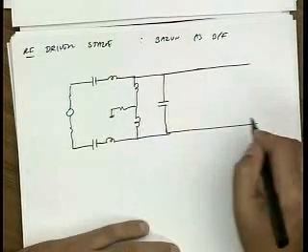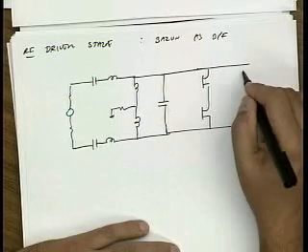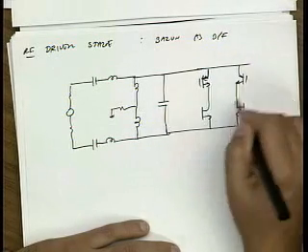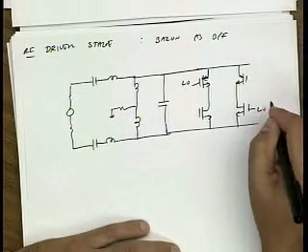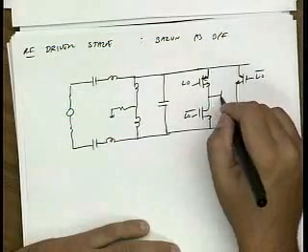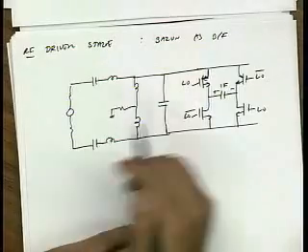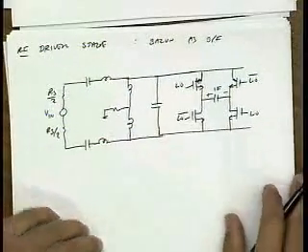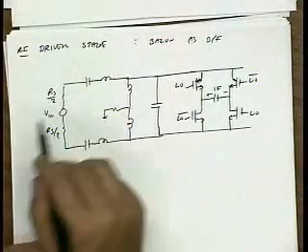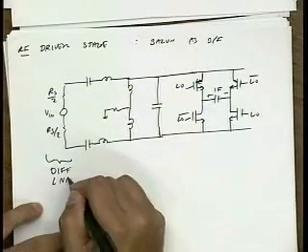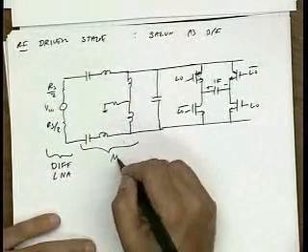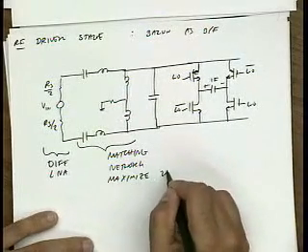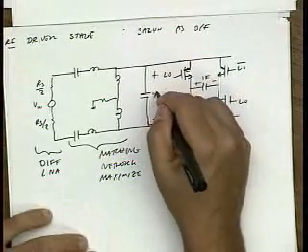And instead of drawing the mixer as a ring, I can just draw it as follows. Let's say this is the all NMOS version. So this is LO, this is LO, this is LO bar, this is LO bar. And let's say this is our IF port, and this is our input voltage. So this is our source impedance divided by 2. So I have a differential signal coming. This might be coming, let's say, from a differential LNA. And what I do here is I have a matching network in order to maximize VRF. Let's call this voltage VRF.